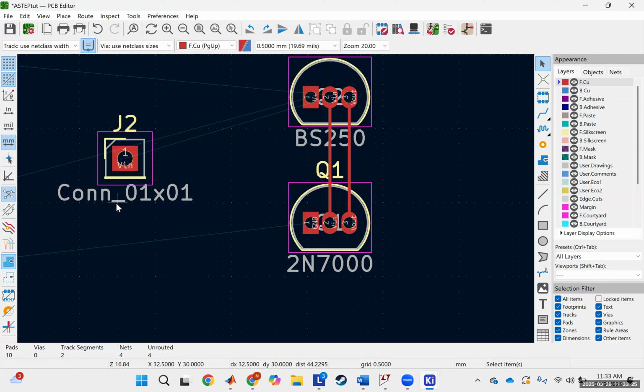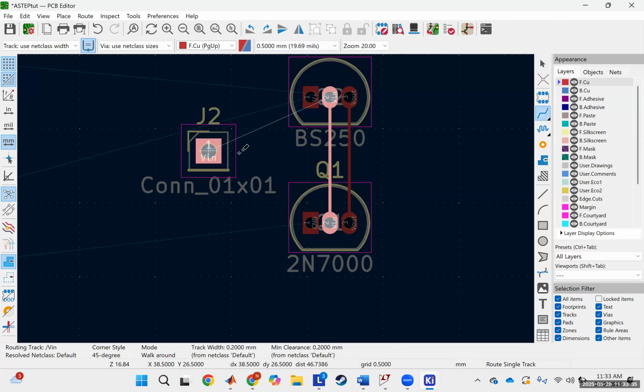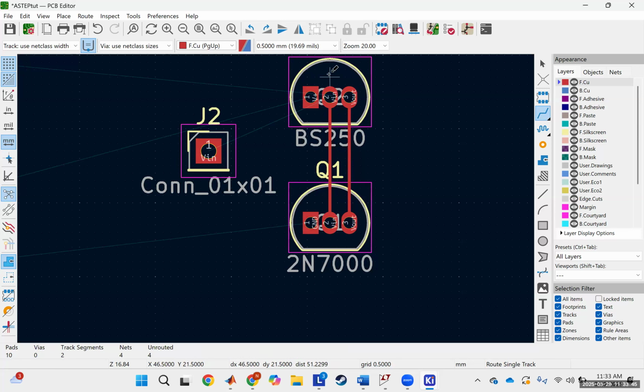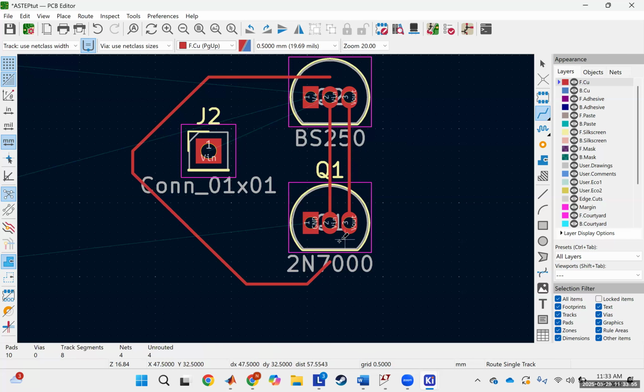Each of these is a copper trace on one layer of your board. So if you had your VN on the other side, you couldn't just run your trace straight through here. It'll be blocked and cause a problem. You'd have to route your VN trace basically all the way around, like this, which isn't super ideal because you're adding a lot of parasitics, but that's not really important for you today.